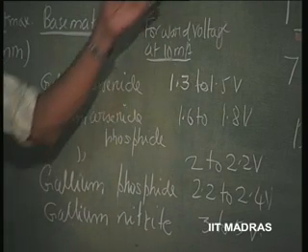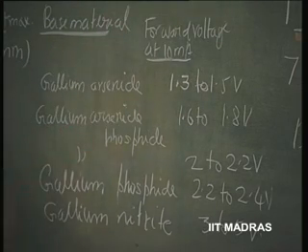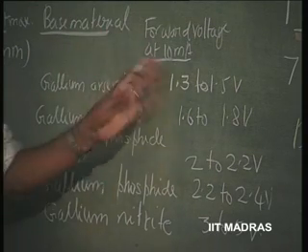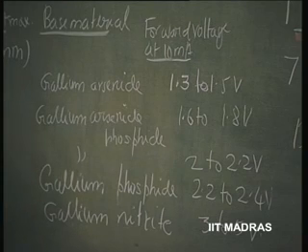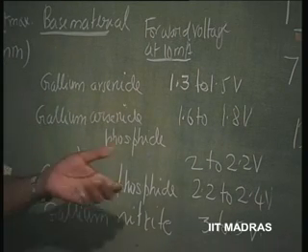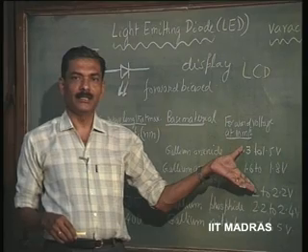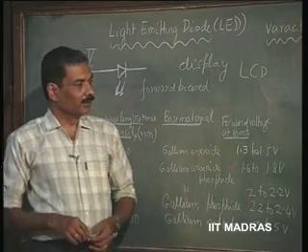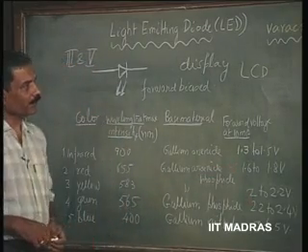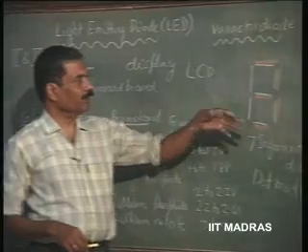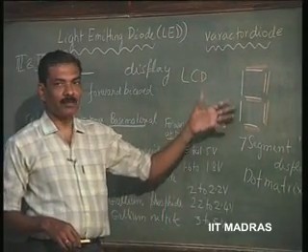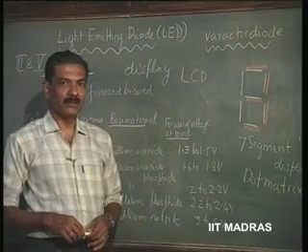So, even though before the advent of LCDs these were being used for displays, with the advent of LCDs, these have gone out of use for most of the cheap displays like wristwatch display, etc. We cannot afford to waste current and power of this order of magnitude. However, for large displays and things like that you do not mind wasting some amount of power on this display, these displays are still being used.